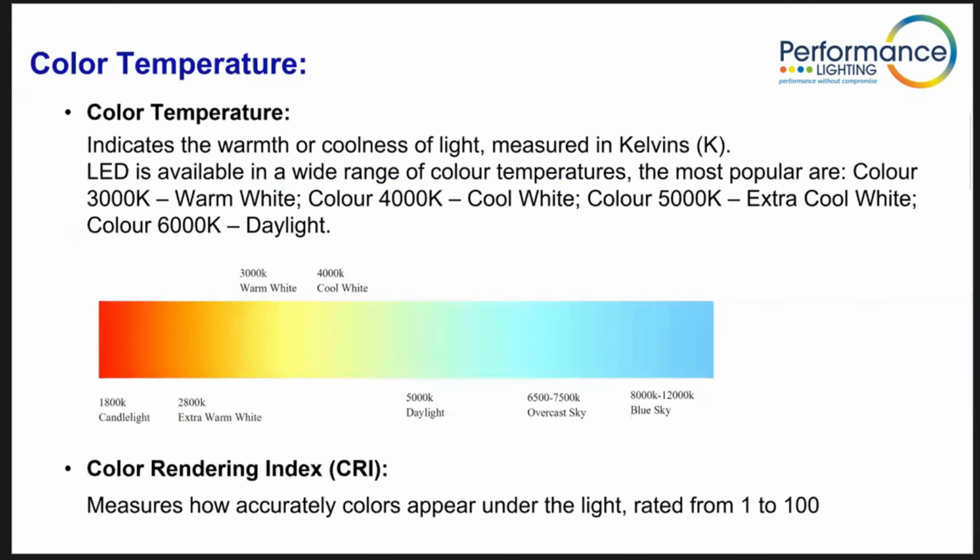So your eye sees that and it looks cleaner in comparison to the warmer yellow 3000K. Then depending on the environment, we can go up to 6,000, 6,500K, which is almost blue, quite clinical white light. Quite often, dentists, hospitals or doctors' surgeries may use something a little bit cooler because it gives the effect of clinical, bright, quite stark light. So colour temperature is really important to think about when specifying the product that you want to buy. That has a big impact.